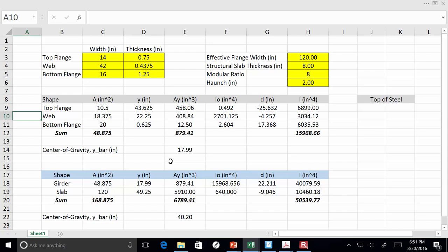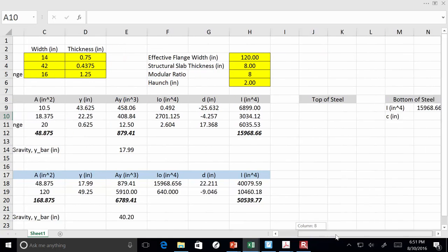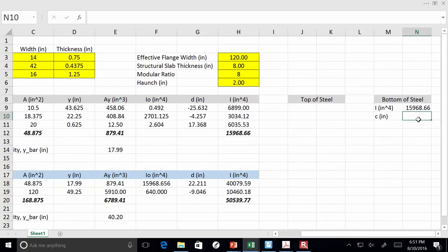So that is our extreme fiber distance right here, and we'll say equals that, right? So our section modulus, which is going to be in inches cubed, right? If I take inches to the fourth and divide by inches, that's going to give me inches cubed. It's just that divided by that. So it comes out to be like 887 point something.